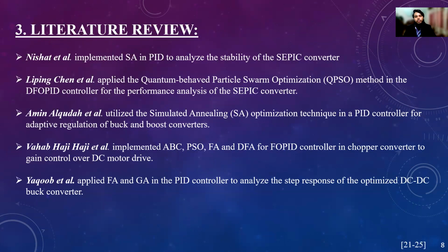In literature review, we found some related works. Nishat et al. implemented SA in PID to analyze the stability of SEPIC converter. Liping Chen et al. applied the UPSO method in the DFO PID controller for the performance analysis of the SEPIC converter. Amin Al-Qada et al. utilized the SA optimization technique in PID controller for adaptive regulation of buck and boost converters. Haji et al. implemented AVC, PSO, FA, and DFA for FOPID controller into chopper converter to gain control over DC motor drive. Yakub et al. applied FA and GA in the PID controller to analyze the step responses of the optimized DC to DC buck converter.